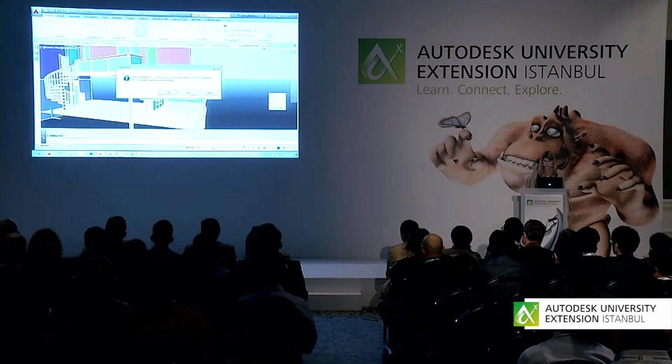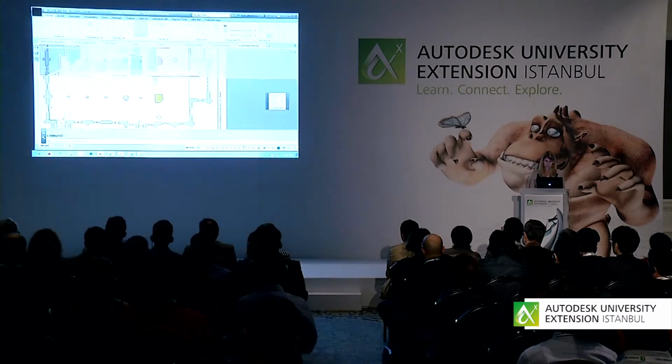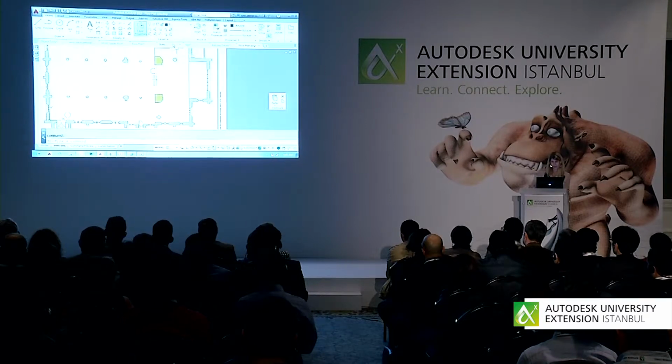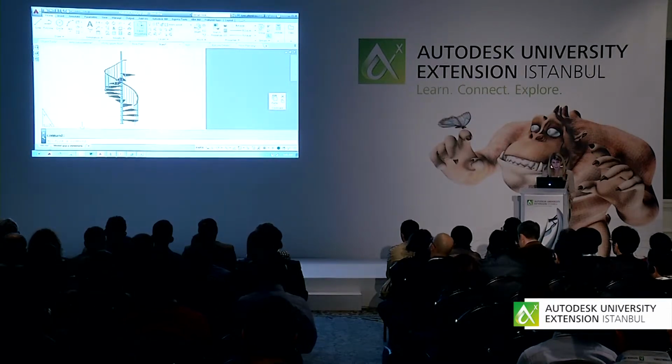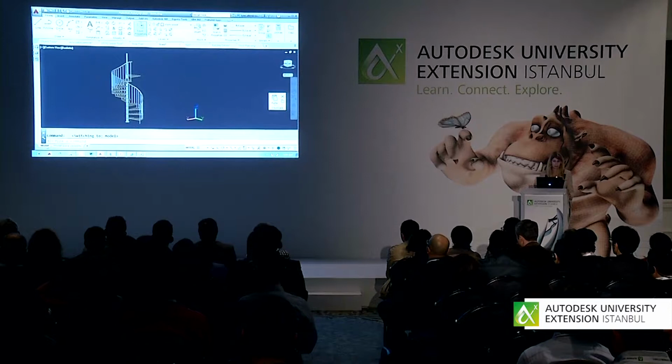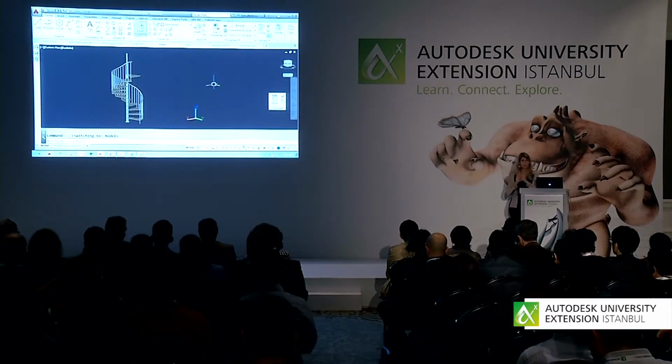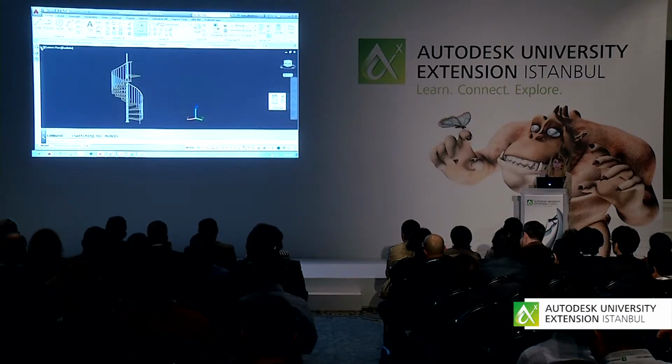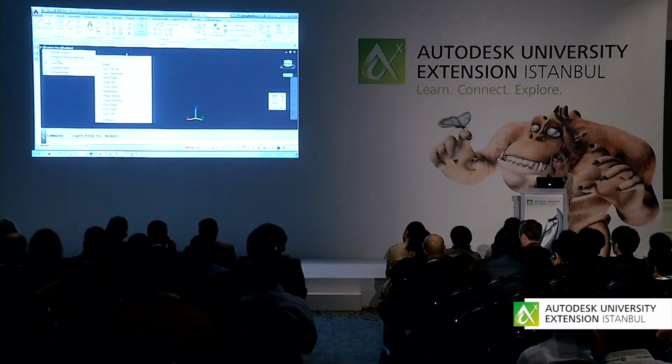Let's close this one too. So I don't know if any of you, let's go to stairs, if any of you use model space viewports. Those are tiled viewports that only work when you're in model space. If you do, some of you, if you work in 3D, you might. I like to get to the model space viewports by clicking up here under viewport controls. You can set up the configuration that you want in this list.